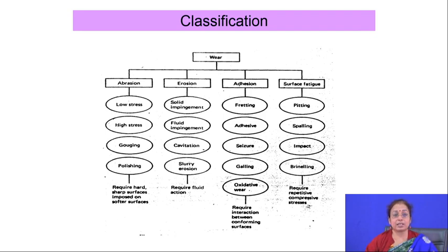Now, wear is a very interesting phenomenon, and in a word you can say that wear is progressive in nature. For wear to occur, there has to be relative motion between two surfaces, and wear is actually measured in terms of the loss of material. Usually, in most wear there is loss of material from the surface, except in a few cases, but there are different ways by which wear occurs, depending on the kind of meeting surface the component is facing, the hardness differences between the surfaces, and the environment the component is facing. So, it is a kind of relative property of the material.